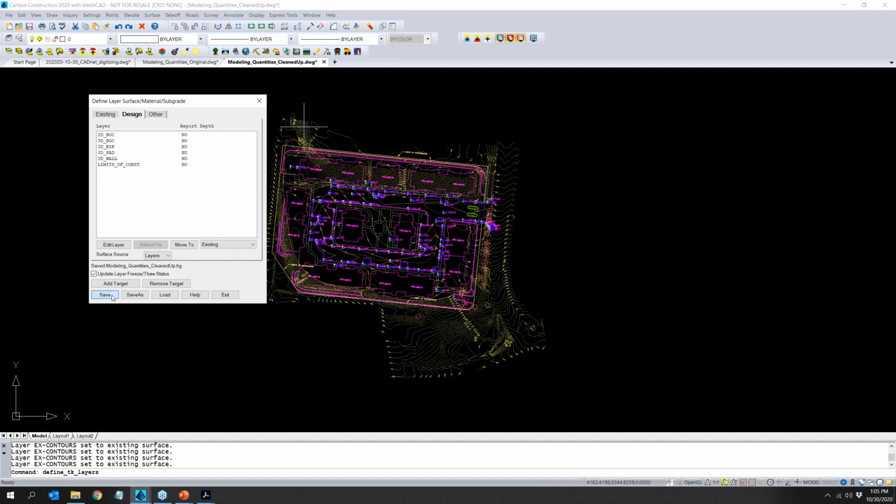It's important to save here because you're saving all this data into this TRG. It's a target file. I haven't really done anything in this drawing; this is where the changes are being saved. So this is important: if you save or archive or have to send this to somebody else, you want to send the drawing plus this target file. Are there any questions on this?